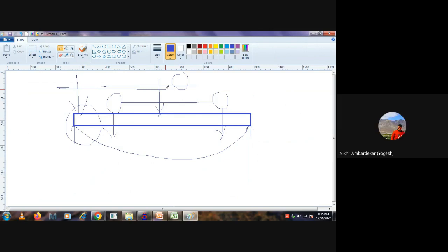So this is a point load. Maybe you can convert it into a plate load also. In that case, you need to find out the contact area of the tire. It is given in IRC, based on the vehicle, H20, HS20. All these things are given in the IRC codes. So the contact pressure, the tire will also have a contact pressure. Yes. So based on that, instead of applying a point load, you can apply a plate load based on that wheel.